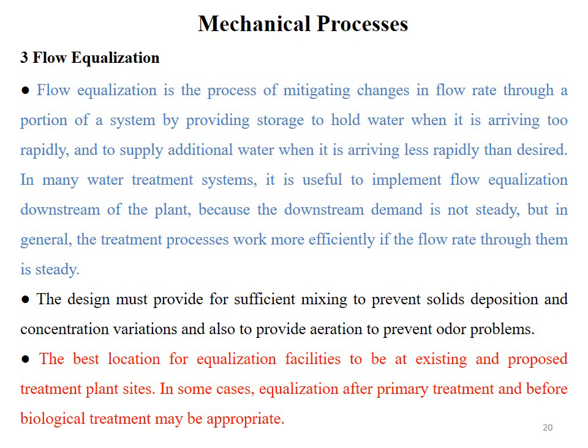And in many water treatment systems it is useful to implement flow equalization downstream of the plant, because the downstream demand is not steady, but in general the treatment processes work more efficiently if the flow rate through them is steady.